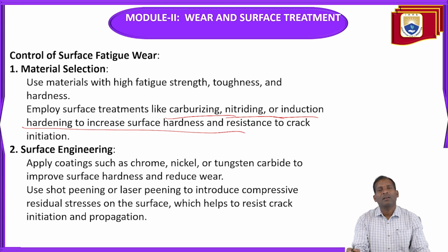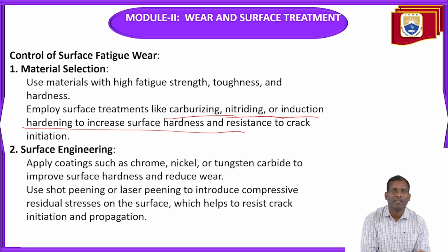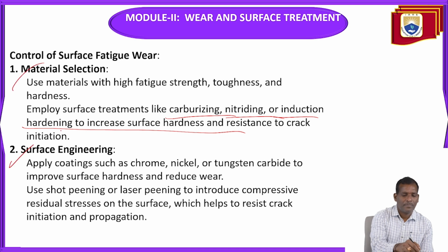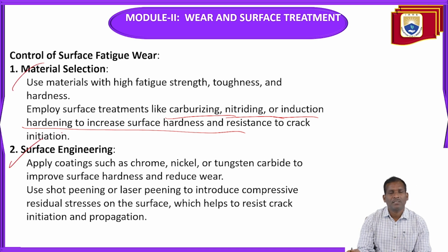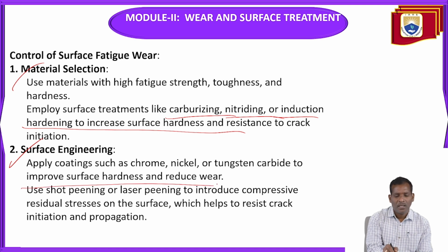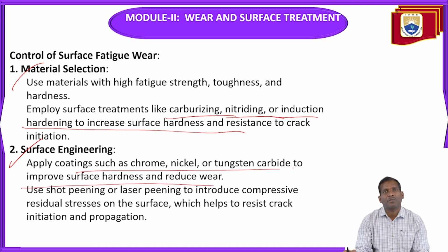These are surface treatment processes that give good properties. Surface engineering: apply coatings such as chrome, nickel or tungsten carbide to improve the surface hardness and reduce wear.